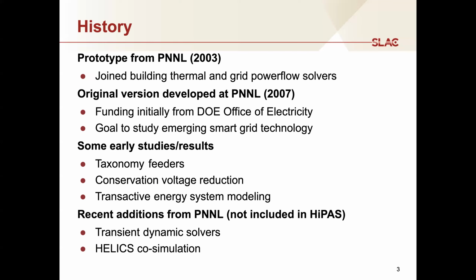Meanwhile, over on the power systems side, the power system simulators tended at the time especially to focus on solving a situation, right? You look at a condition, for example, a scenario on the power grid, and you might study the dynamic transient response of a system to a fault, or you might study the steady state power flow solution under a particular range of scenarios so that you could optimize, for example, power flow or some such thing.